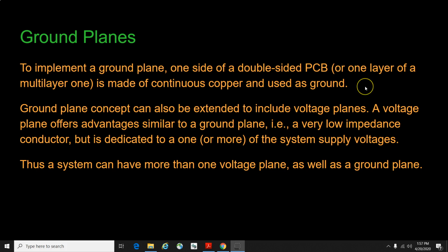Such a ground plane offers the best possible conduction in terms of minimizing any false ground difference voltages across the conducting plane. See, the importance of maintaining a low impedance on a large area ground plane is critical to all analog circuits today.